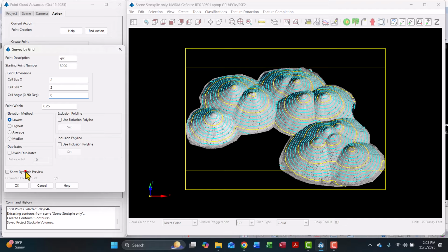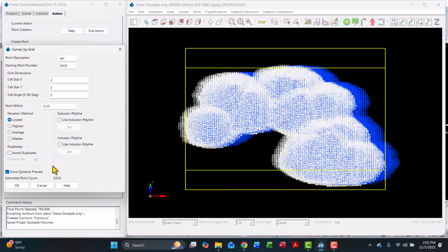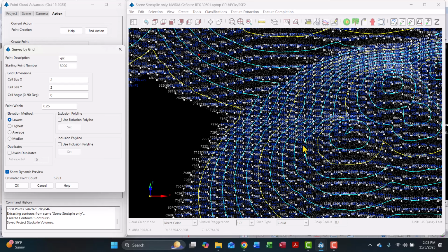Now we're doing it on the point cloud that we isolated, so we're just extracting that little area. For the rest of the site, we can come back later to the other one, do an exclusion, and just extract maybe not at a 3 by 3, but maybe at a 50 by 50, right? And then once we have all the points, we'll triangulate in CAD and generate a new set of contour lines. And there we go, it's done. We have all the points in there. So we're getting that many points.